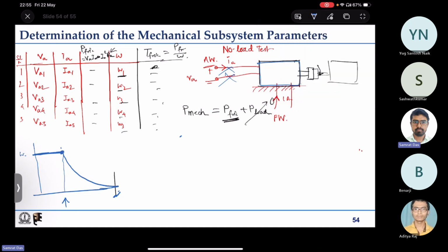So if we disconnect the motor or the supply, then the torque will fall to 0 immediately, because if you open the circuit, current is 0 instantaneously, so that means the torque is also 0 instantaneously, right? Or not exactly instantaneously, but with respect to the mechanical time constant, it's almost instantaneous.